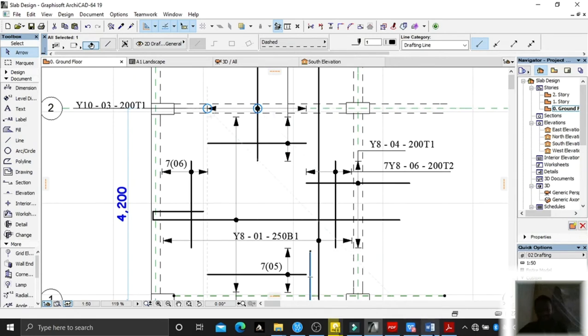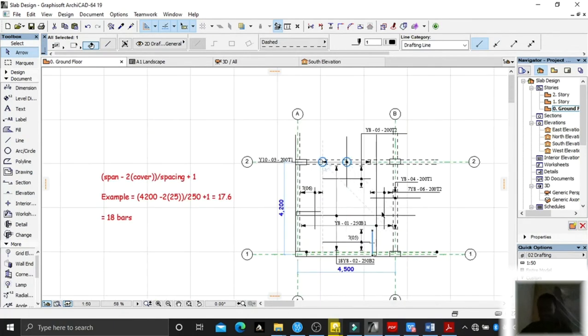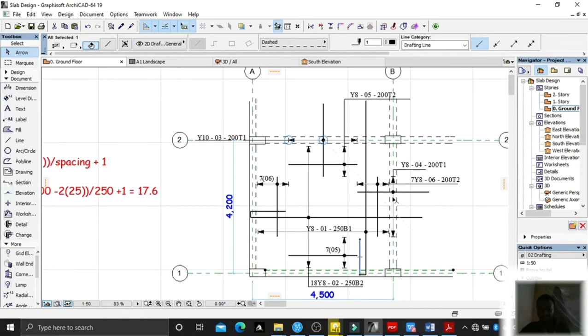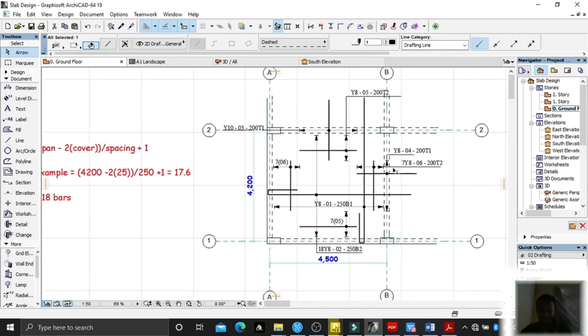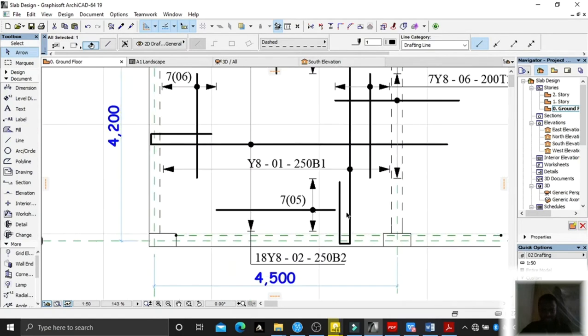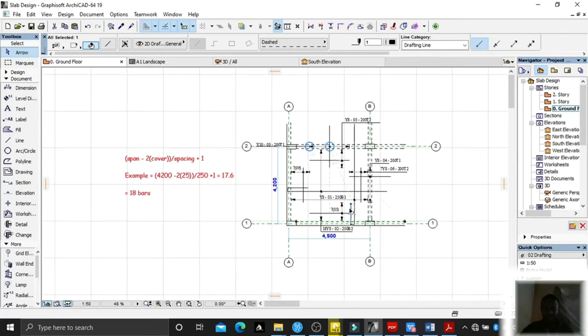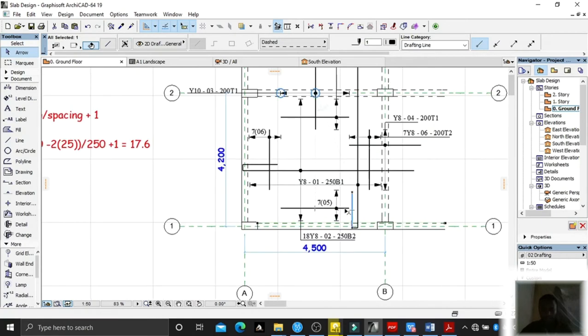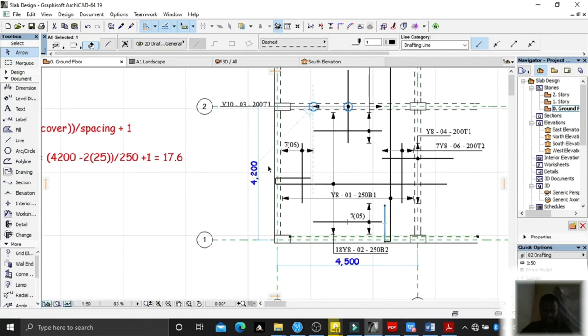Just realize and understand that this is what is rising, where you have a continuous edge. We have these bars acting as top 1, slicing the beams, 25% clearance on this end, 25% clearance on this other end. On these discontinuous edges, our top 1 becomes this clamped end. As you remember, we clamped again 25%. So that now becomes our top 1 bar, and the same goes to this other end.